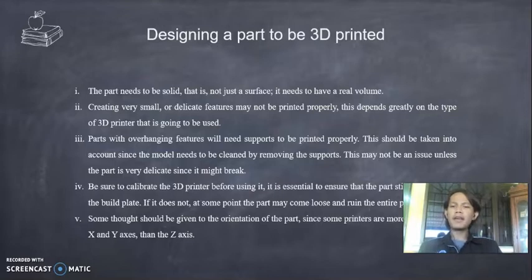Third, if the part is overhanging, features will need support to be printed properly. This should be taken into account since the model needs to be cleaned by removing the supports. This may not be an issue unless the part is very delicate since it might break.